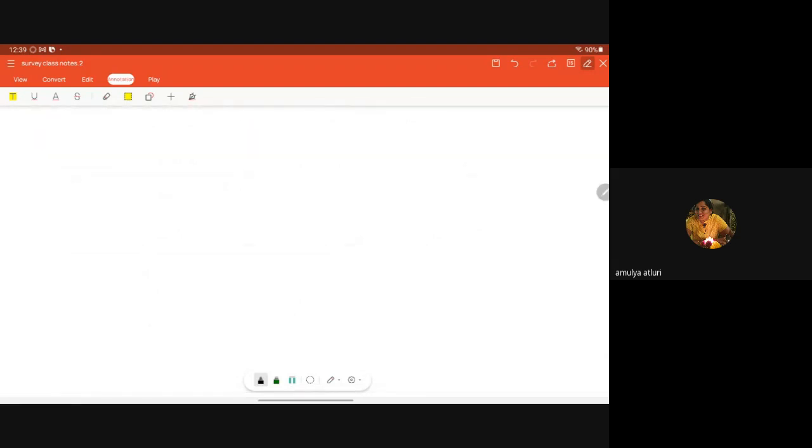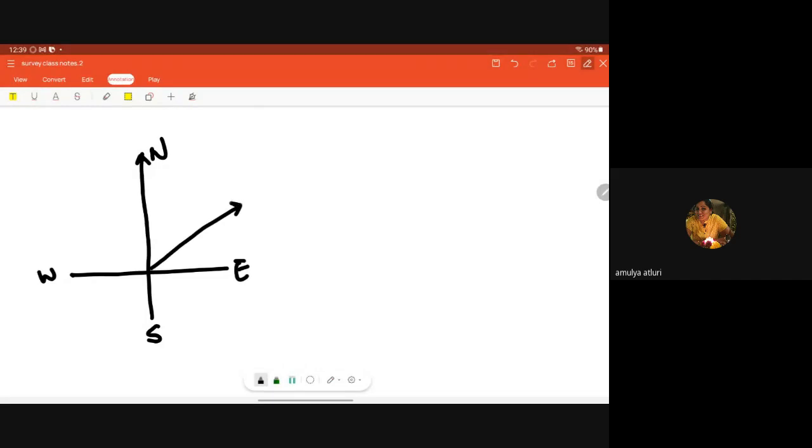Now we consider eastern declination. We'll draw one line: north, east, west, and south. This is your north, and the true north is here. This is your TB, true bearing, and here is your magnetic bearing. This is my survey line.